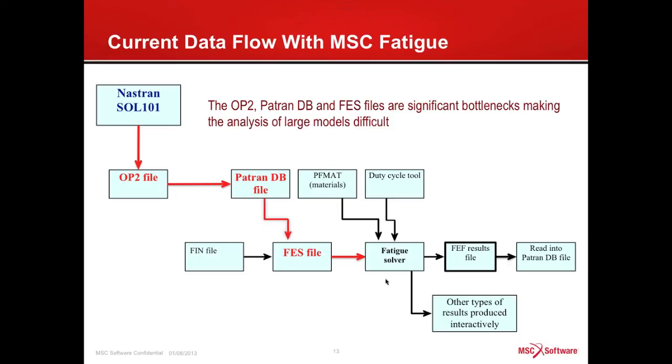In Patran, in MSC Fatigue, it takes place in two steps, because first of all, you connect the stresses to the Patran database. And then the second thing you do, once you start to define your fatigue job, you specify all of the various parameters that you want to use in the fatigue analysis, get to a point where you run the fatigue job. And the first thing that happens is that Patran or MSC Fatigue reads the stresses and conditions them and puts them into another file called an FES file.